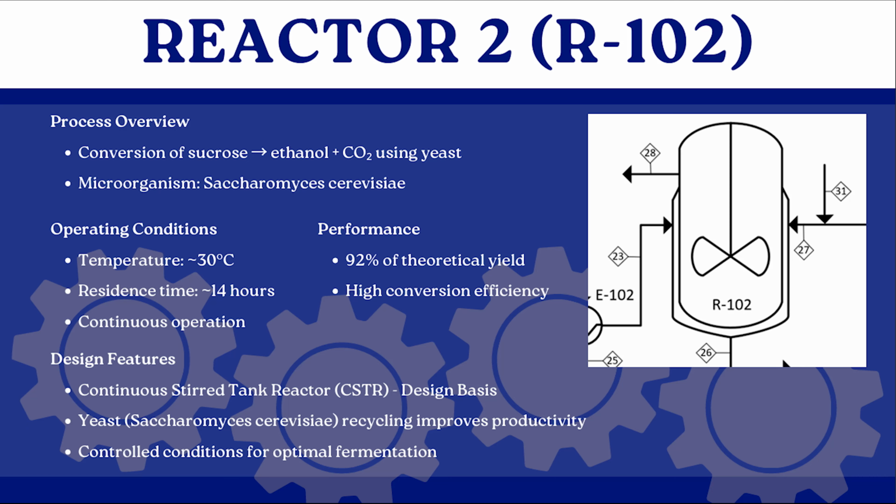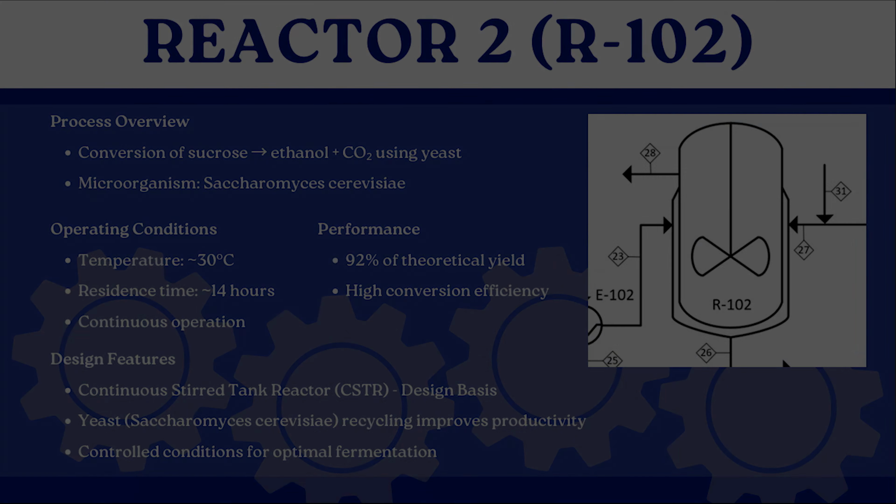The reactor operates at approximately 30 degrees Celsius with a residence time of around 14 hours, allowing efficient biological conversion. Based on the design assumptions, the reactor achieves approximately 92% of the theoretical ethanol yield. In addition, yeast recycling is incorporated to improve productivity and reduce fresh catalyst consumption.